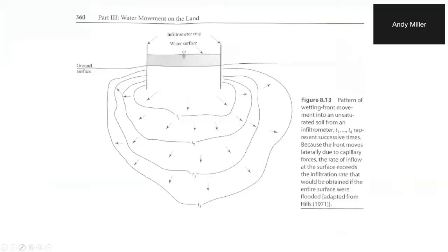Well, I'm going to make it impossible to give that answer so I can move in the direction I want to move. That's a plausible answer. But let's assume we have homogeneous material and that it's not a function of differences in the soil itself. Liza. I mean, it's literally just drier on the outsides, and the water is going to go. Right. So the water will go down a gradient, right? It'll go from higher moisture content to lower moisture content.